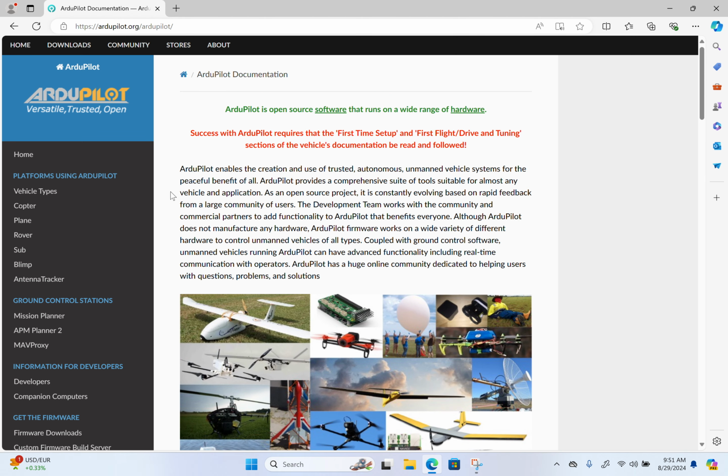They have to speak some sort of a language. Typically, the drone will give out its GPS position. It might give its throttle setting. It might tell you its orientation, its temperature. And then the ground control station will take that information from the drone and plot it on a map on your computer. And then the ground control station may send commands in the other direction up to the drone, for example, fly to some point, or rise or descend, or change your mode, or something like that.